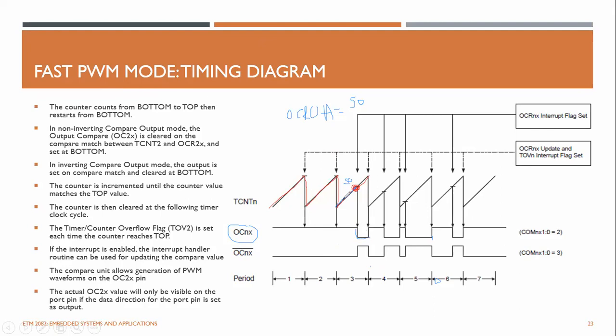And now the timer is still counting, right? It will count to 255 and reset to 0. In the CTC mode, we saw the timer is reset, but here it is not. The timer is not resetting. Instead, it will just keep counting up to 255. Then it goes to 0, and it is counting up.